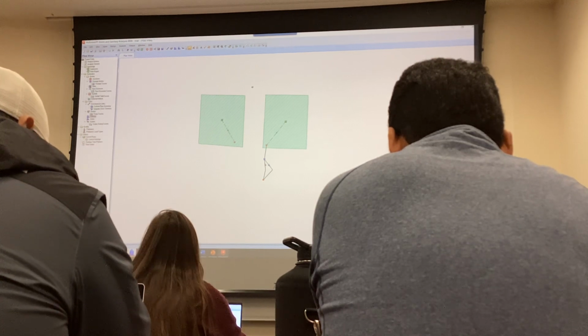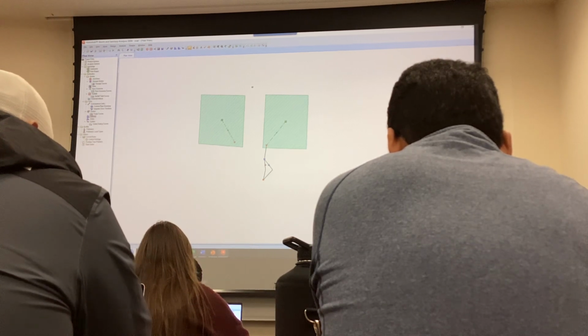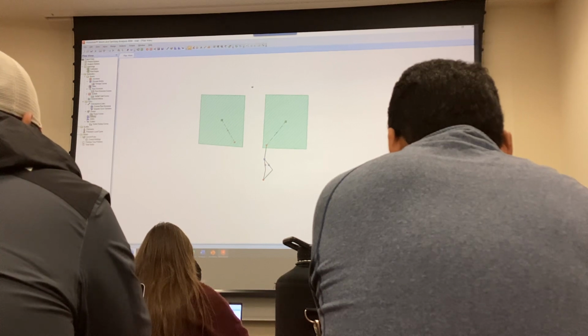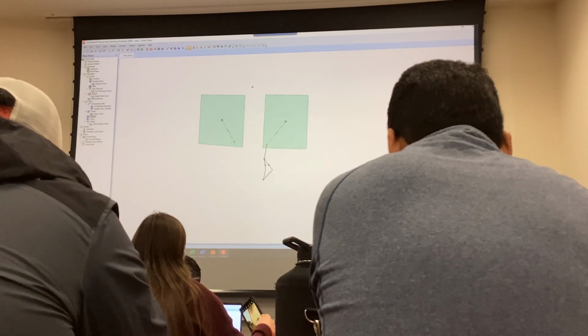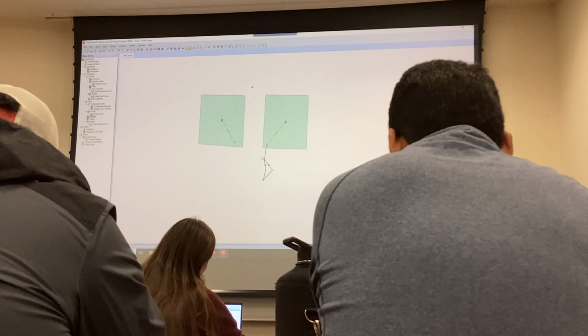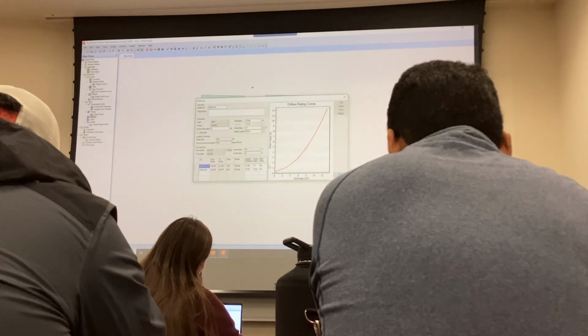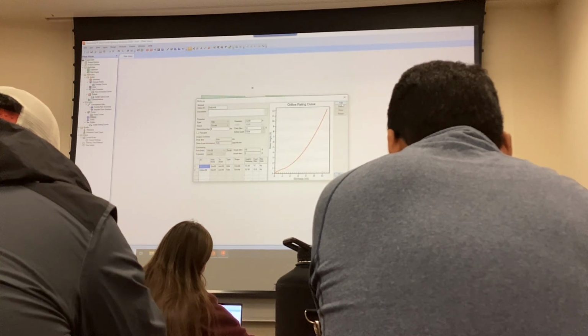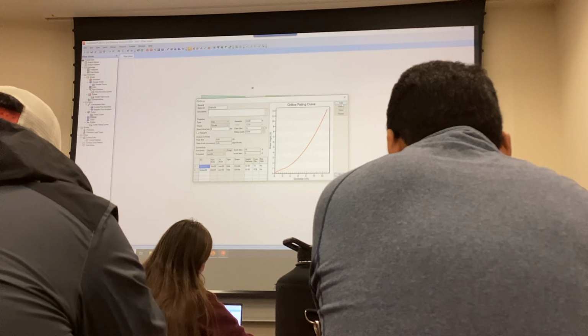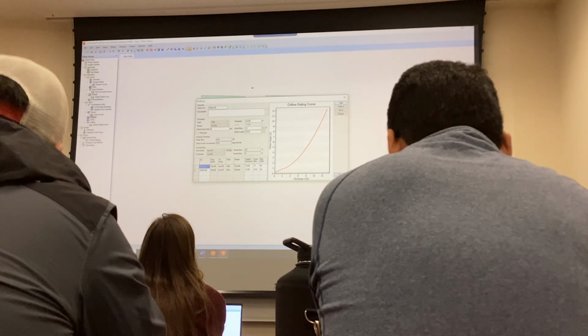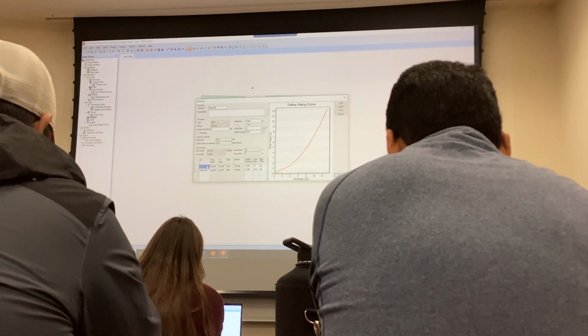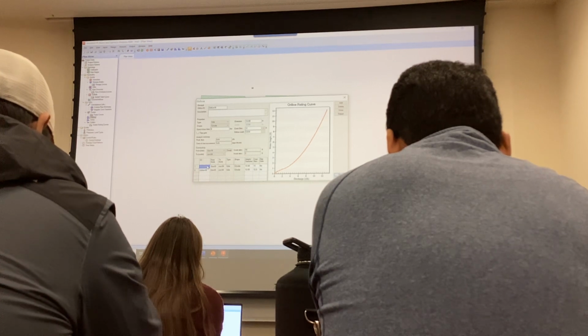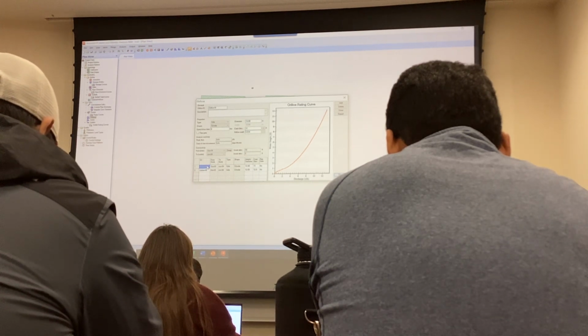Now, if you desire to have the exact same orifice at the exact same elevation, then what you want to do is instead of adding like 10 different orifices, you can just add by clicking add over here for orifice number 1. So you can specify how many barrels you want simply by doing that.